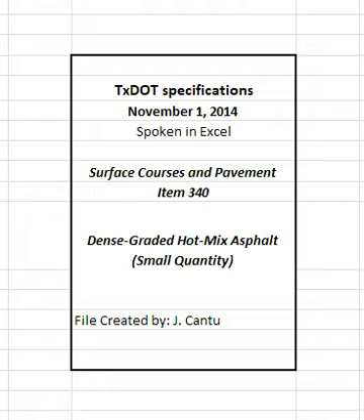4.8.4 Individual loads of hot mix. The engineer can reject individual truckloads of hot mix. When a load of hot mix is rejected for reasons other than temperature, contamination, or excessive uncoated particles, the contractor may request that the rejected load be tested. Make this request within 4 HR of rejection. The engineer will sample and test the mixture. If test results are within the operational tolerances shown in Table 11, payment will be made for the load. If test results are not within operational tolerances, no payment will be made for the load.